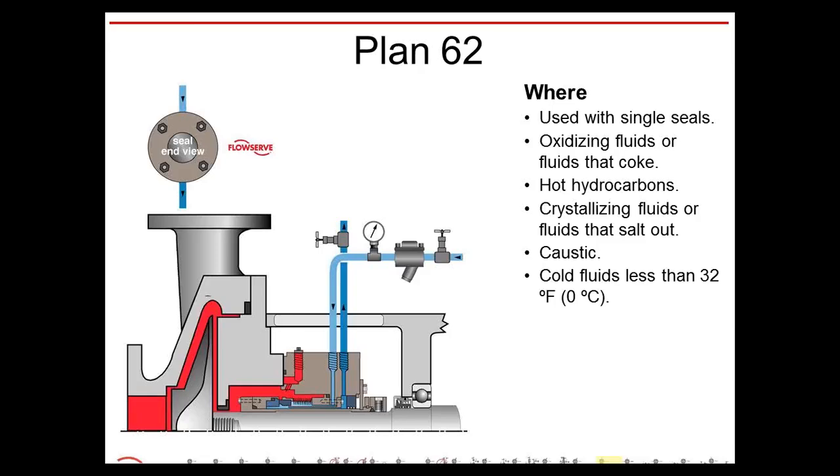Again, used with single seals. It's only used with single seals. It's used with oxidized fluids that coke, hot hydrocarbons, just like I mentioned, and things that salt. I forgot about that. A lot of crystallized fluids that salt, caustics, and of course, cold fluids less than 32 degrees Fahrenheit.